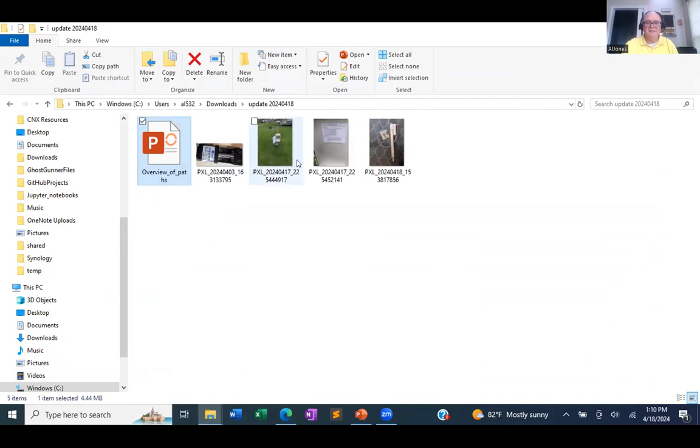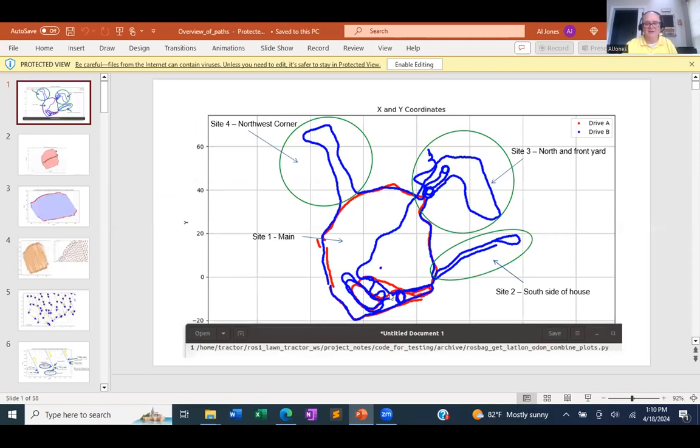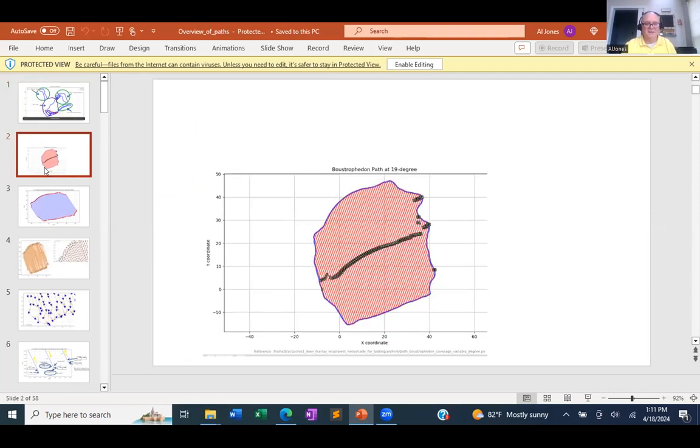So my next step is, as I mentioned, to take the ROS bag file that I've got, which includes both lat long information as well as X and Y data, and pull the X and Y coordinates off the pose statements. Visualize that, figure out which of those makes up my perimeter, and then pseudo adjust that. Once I'm happy with the XY perimeter, I can rebuild my path and get back to proper testing.